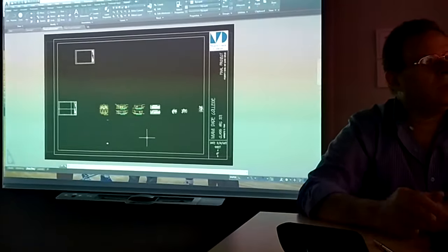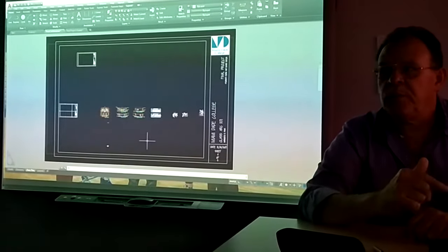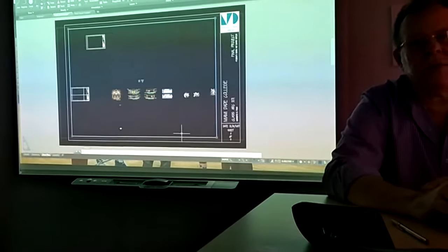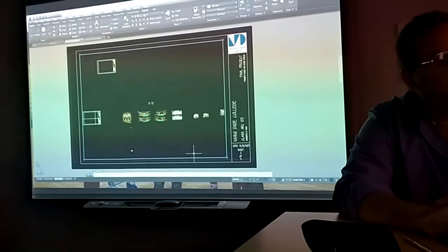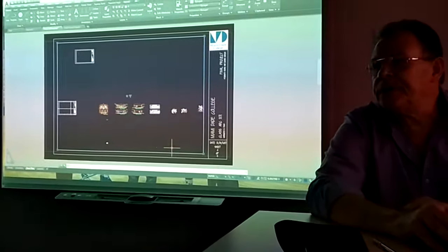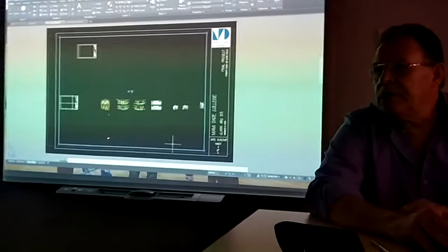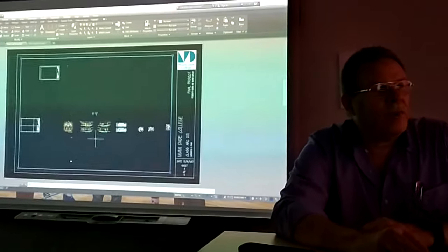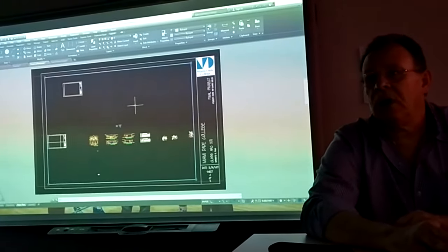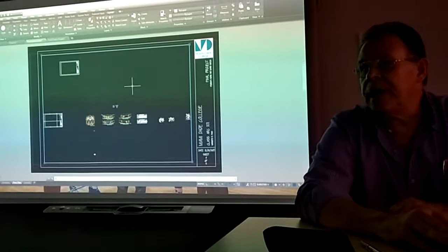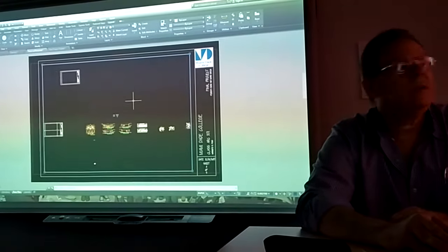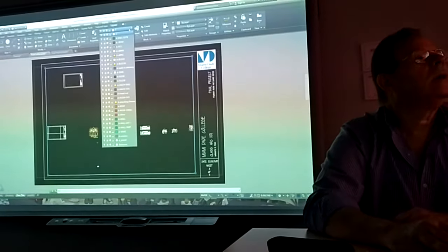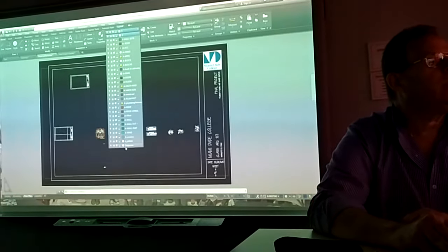Okay, so to activate the portal, which is a viewport, remember this viewport has a window here. If I highlight the window, I need to put it on a viewport layer so that it won't print. Because if I have a floor plan here with this rectangle, it's going to look ugly. It's not going to look nice. So you want to hide this rectangle. So there's two ways of doing it. Either you put it on depth points,